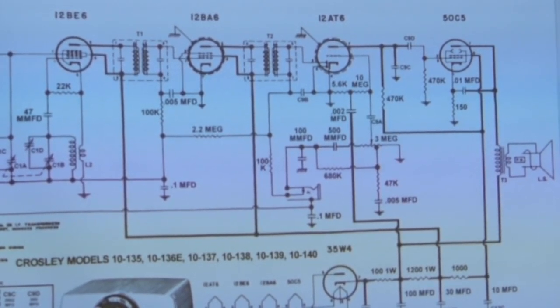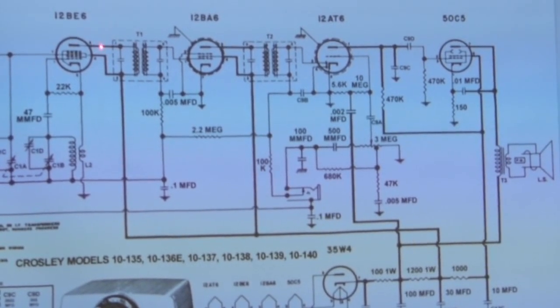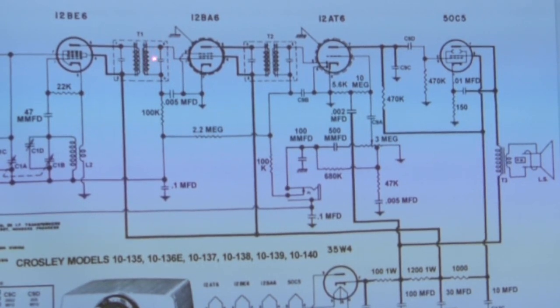But if you don't have a scope, you have your signal tracer and you set it here, no signal. And you might go here and you might be getting some jumbled radio signals, but you're still getting something. So something has happened between here and here. The possibilities are that you have a shorted turn or something in the IF can and it's collapsing the inductive field, or you have an open IF can.